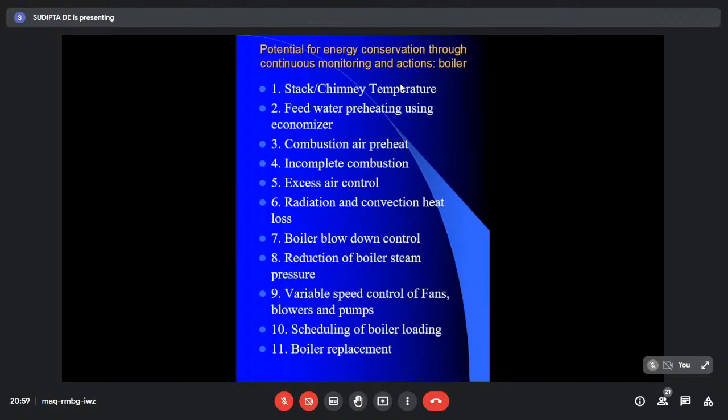I'm just telling you the symptoms, not the measures to take. I'm saying proper measures should be taken. But what is a proper measure? It's difficult because many technological options are there. You have to control it, increase the turbulence, increase the temperature, use staged combustion. I'm not going into those things, it is not possible in a mixed group, but you can identify that incomplete combustion can be identified by two aspects: one from the flue gas analysis of carbon monoxide fraction, and the other from ash sampling, where you can find solid carbon in the ash itself.